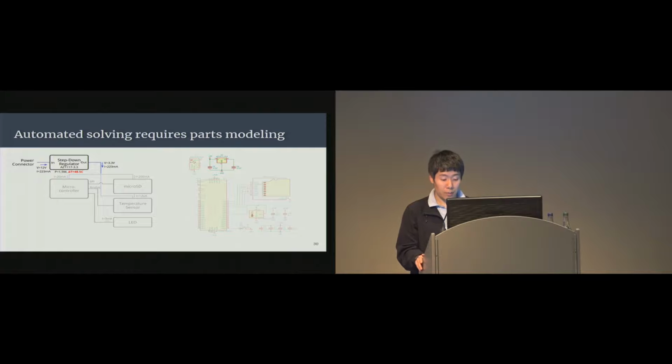However, the intelligent part requires a model of electronics to ensure a correct circuit, such as obeying maximum part ratings. For example, if we decided to use that linear regulator there, its inefficiency would lead to excess waste heat and result in a very toasty component. But if we use the switching buck converter, its higher efficiency makes thermals much less of a problem. And once we have settled on a topology and parts, getting a schematic out is just a matter of dropping in its subcircuit.